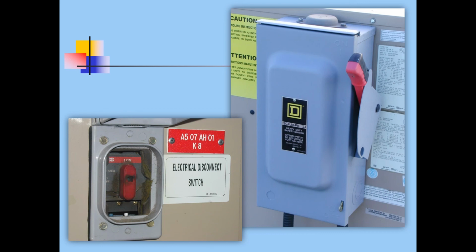A disconnecting switch is required for all units, and what we must pay attention to is how many live lines we have. Is it a single phase unit with 2 hot wires? Is it a single phase unit with 1 hot wire? Or is it a 3-phase unit that would have 3 hot wires? These are all different things I need to consider, as well as what is the amperage rating of my circuits. My disconnect switch must be rated for not only the voltage and the amperage of my circuits, but we also need to make sure that they are mounted within sight and within 3 meters. Typically, they're installed on the side of the air conditioning unit in a convenient place that you can work on it safely.